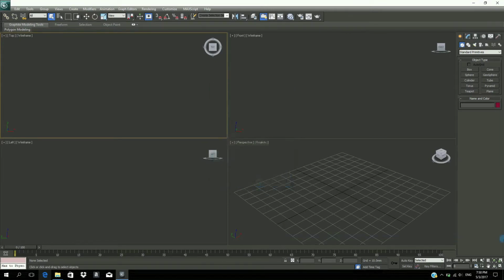We'll press OK. We'll make sure that our snaps toggles are on 2.5, so we'll click on it. When we click on it for a long time, a flyout menu appears and we can choose 2.5. We'll right click on the snaps toggle and make sure that endpoint is chosen. Let's assume it wasn't, then I'll just need to click on clear all and click on endpoint so that it snaps to the ends of objects. You'll understand this when we go further into the AutoCAD plan.